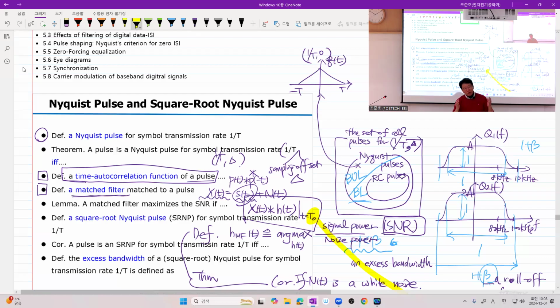However, if you want to design a radio communication system where the channel attenuates your transmitted signal, antenna combined with channel attenuates the signal around 100 dB, so that your receiver must amplify this very weak signal a lot so that your thermal noise could be observed, like long distance communications. In that case, you need to use a square root Nyquist pulse in the transmitter and modulate your carrier. And in the receiver, you use the matched square root Nyquist pulse and process.